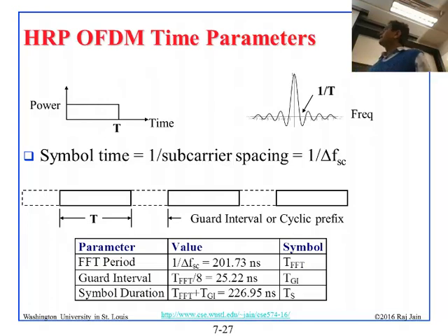An impulse in the time domain is a unit function in the frequency domain and vice versa. When we study the fast Fourier transform, all of this becomes clearer, but we are not going to do that. But at least it is clear that the width of this pulse is 1/t. So as we increase t, this will become a very narrow kind of power function in the frequency domain, and it will become an impulse at t equal to infinity.